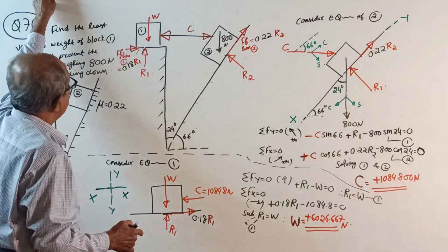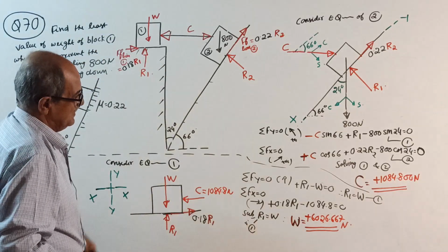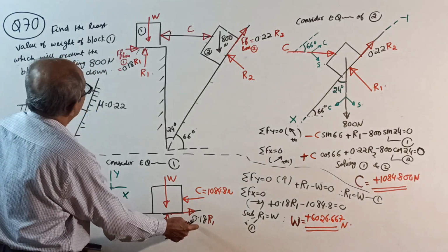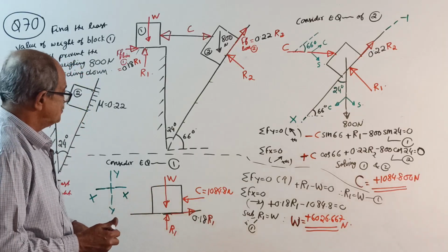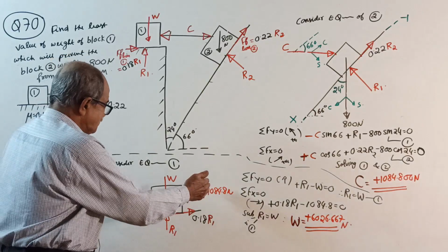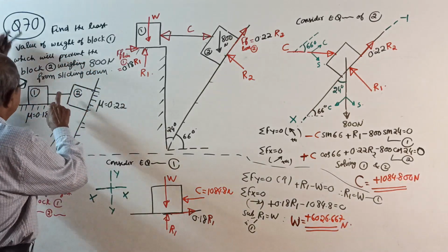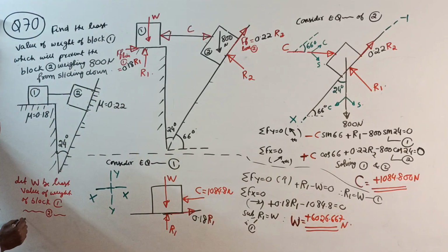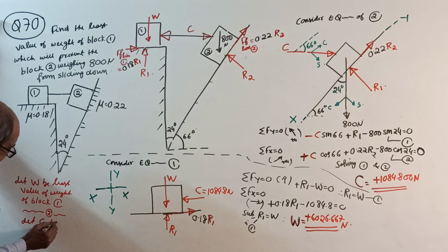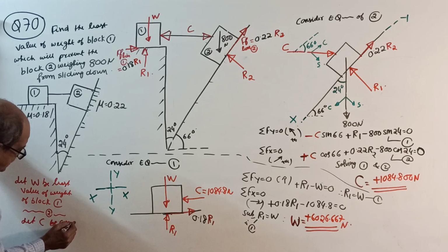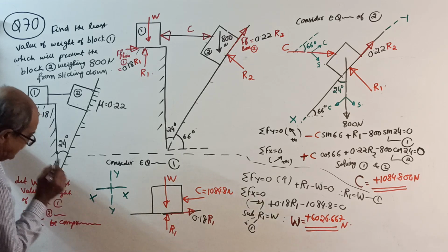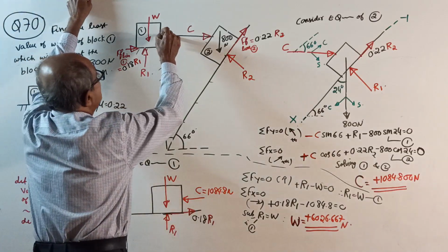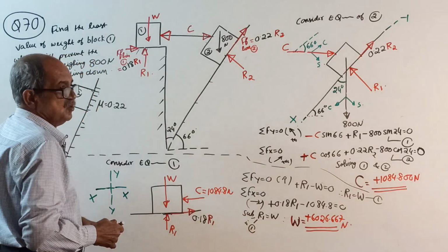Yes, correct. Even if I took left side, when I calculated, I took right side only. Because when I am solving, I know that it is going to push left side. Now, 100% this connecting member will be in compression. So next write, let C be the compression force in the member connecting the two blocks 1 and 2. So compression is like this. So show it here.